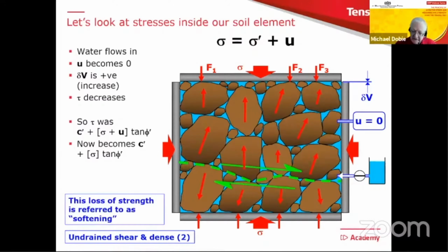And that's a situation that we call softening. That loss of strength due to an inflow of water in this situation is what we call softening. You'll often hear that term used in soil mechanics. So this material is softening, and this is the reason why.